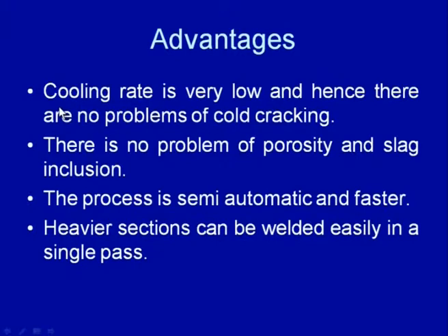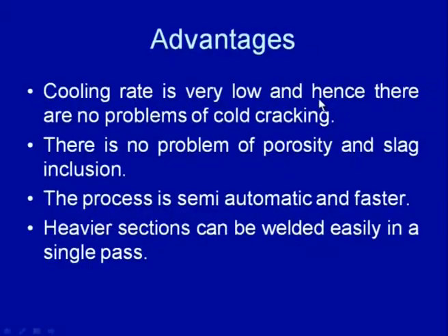And so, the high heat input associated with this process results in a low cooling rate, and the low cooling rate reduces the tendency of cold cracking, which can be encountered during conventional arc welding because of the high cooling rate, and so the tendency of hard and brittle martensitic transformation and high residual stress development. So, the high heat input causes the low cooling rate, which in turn decreases the cold cracking tendency, and the low cooling rate increases the solidification time.